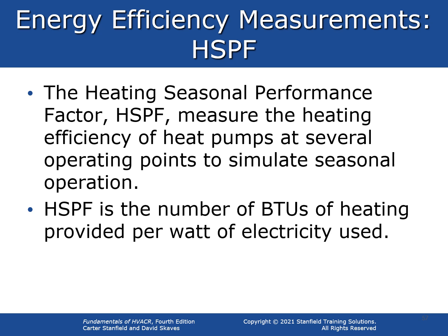The Heating Seasonal Performance Factor, HSPF, measures the efficiency of heat pumps. The HSPF is the number of heating BTUs per hour that a unit produces for every watt of electricity used over a season. Readings are taken at several operating points to simulate seasonal operation. A heat pump's HSPF is typically lower than its SEER.